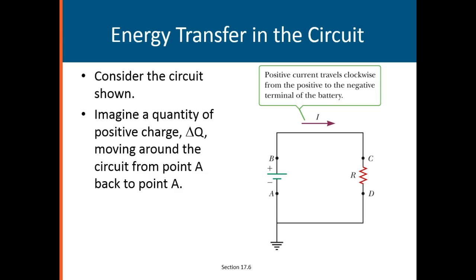Now, over here you've got a resistor, okay? If this wire is a great conductor, in other words, not losing much energy at all, then the voltage difference between A and B will be exactly the same as the voltage drop. Here it's an increase going from A to B. Here it's a decrease going from C to D. Because B is at the same level as C, A is the same level as D, so if this is increasing going this way, it's decreasing going that way with the current.